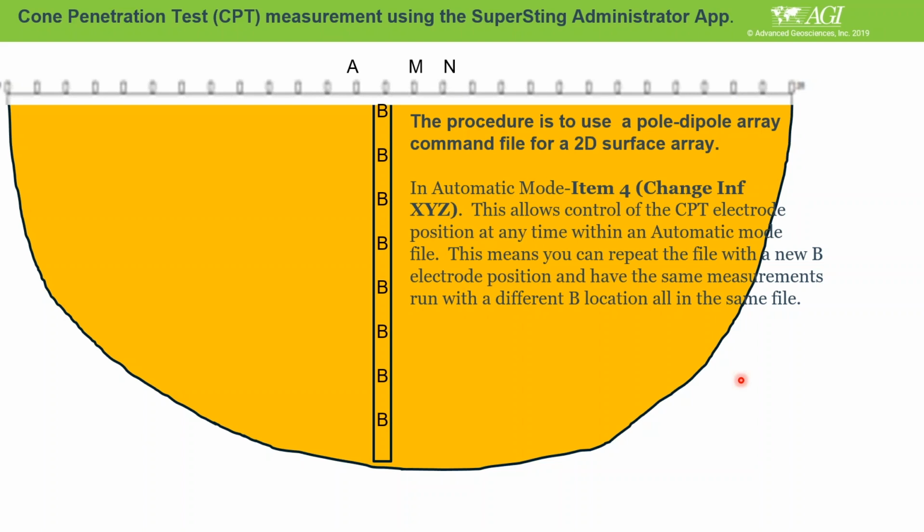You get that from resistivity values. Typically, with a 4 electrode setup, A and B are inside the ground and N is outside. You put the B electrode in the ground and get a measurement, and then put B deeper and get another measurement.